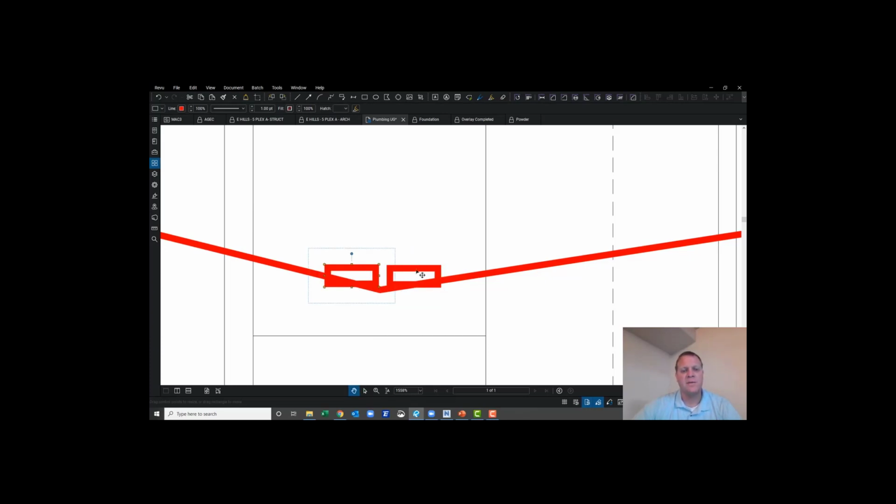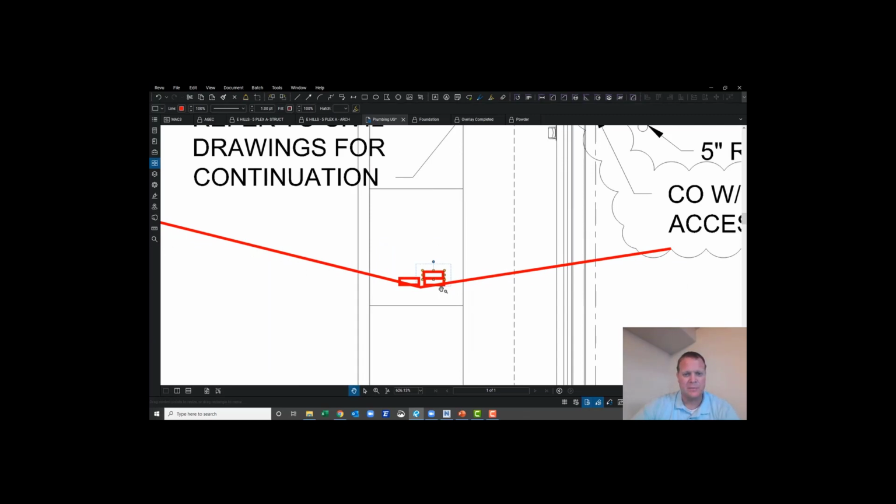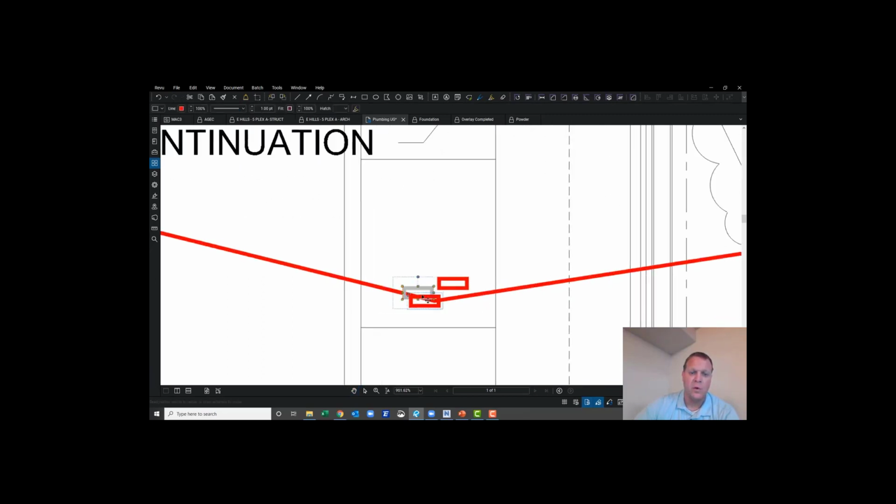They can either be offset vertically, or there can be a ring on top of this one. So we're just going to say that one is higher than the other. And the idea is that during a normal rain event, water on the roof as it comes down collects in the lower roof drain, or the primary roof drain. We'll put that one there.